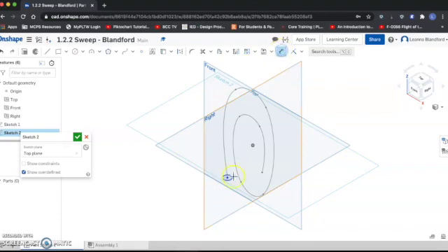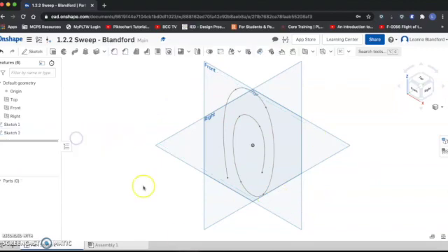Now, the true diameter of a paperclip is very tiny. It's actually 0.031 inches, and that's going to make a very tiny circle, but it will serve our purpose. So I'm going to grab my circle tool again, and I'm going to come over here and do the same thing around this point. So I am going to dimension to that very, very small dimension. And again, they're very tiny. That's okay.